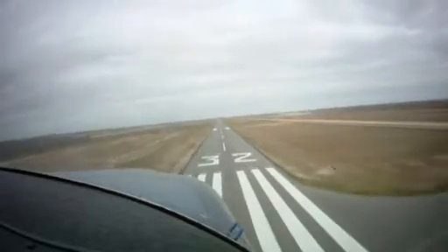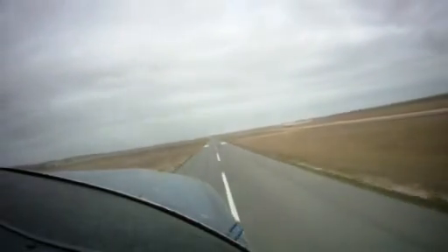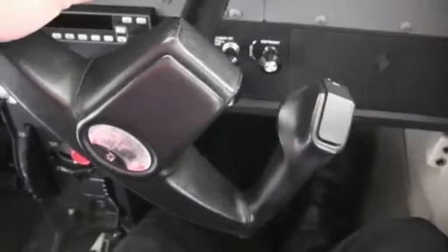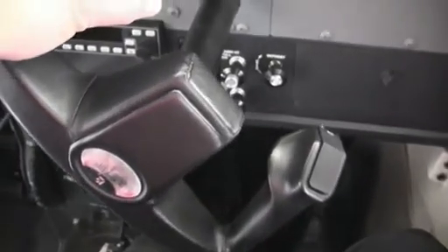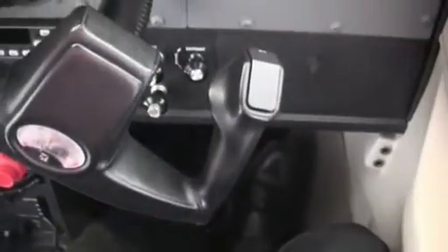Since the wind conditions prevailing were very strong and crossing. To use the side slip method, the pilot aligns the airplane nose with the center line of the runway, notes the rate and direction of drift, and then promptly applies drift corrections by lowering the upwind wing. The airplane will have the tendency to turn in that direction, so it will be necessary to apply sufficient opposite rudder pressure to prevent the turn and keep the airplane nose aligned with the center line.